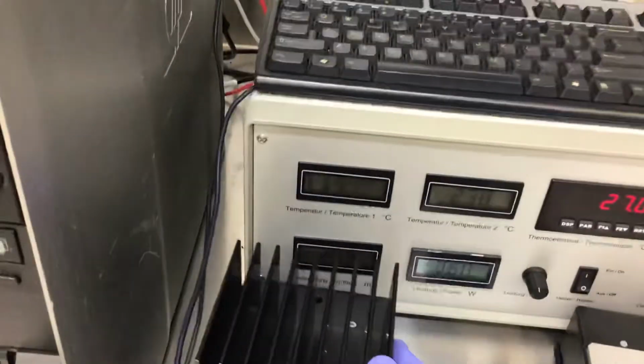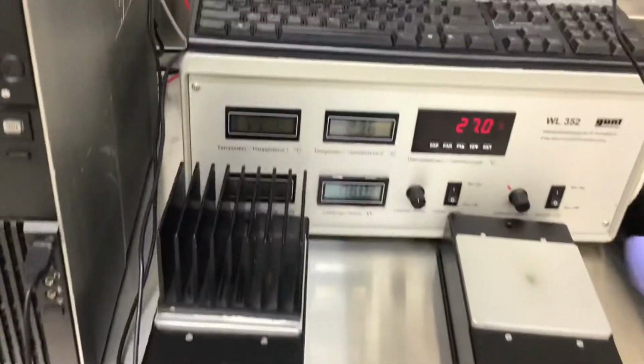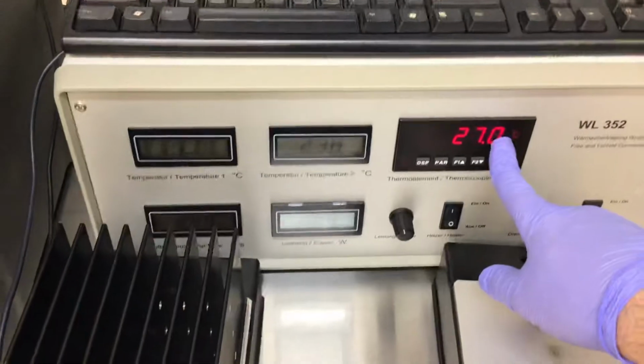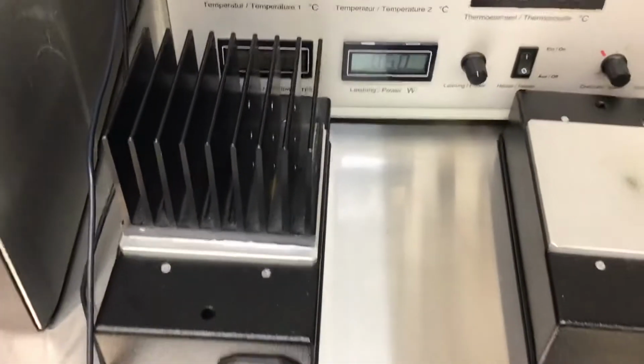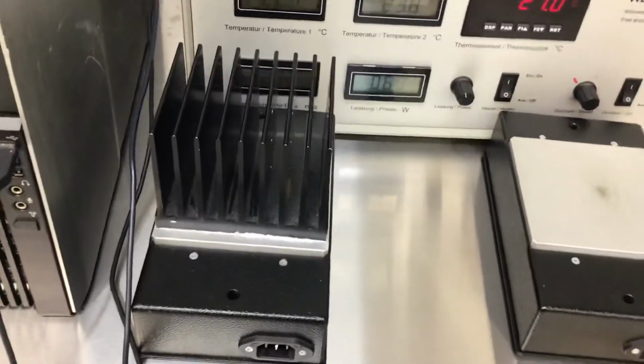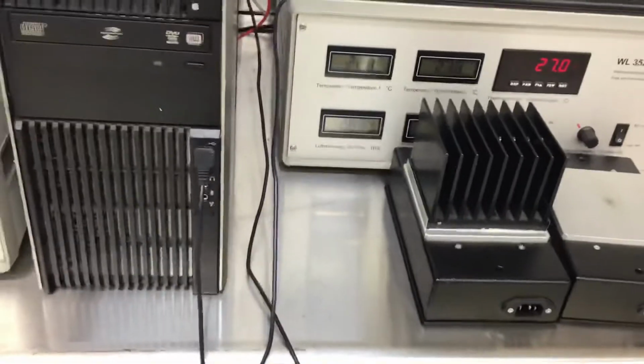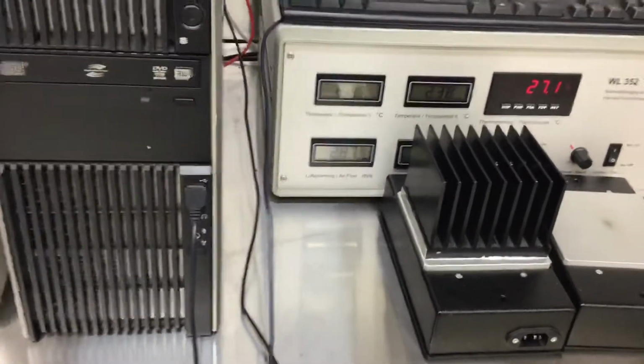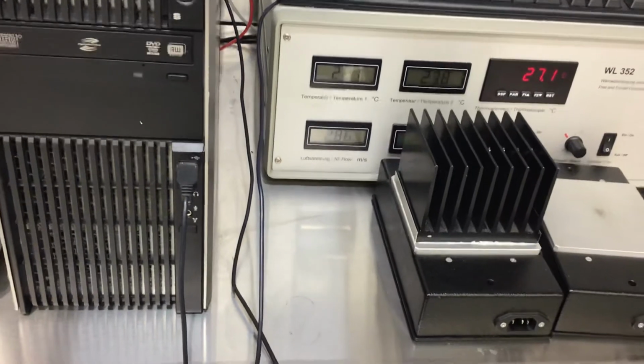Here are two temperatures: the surface temperature, which is the one with the thermocouple on the right side here. We have the electrical power that you set up. Now it's at 60. You want to keep monitoring these values because sometimes the controller doesn't set to a very specific value. You want to get the right average, as well as the fan speed, which is measured by the flow speed inside the duct.